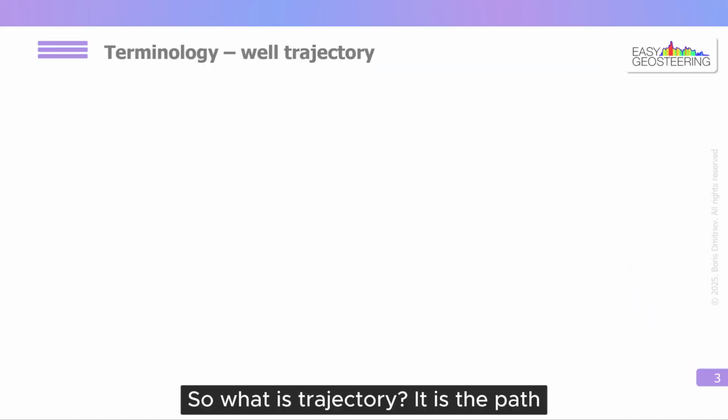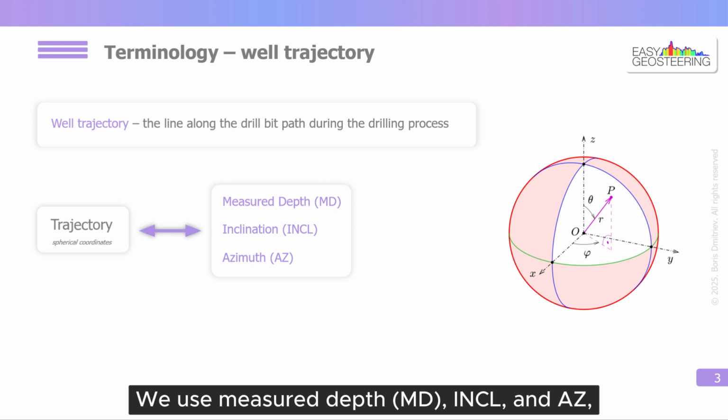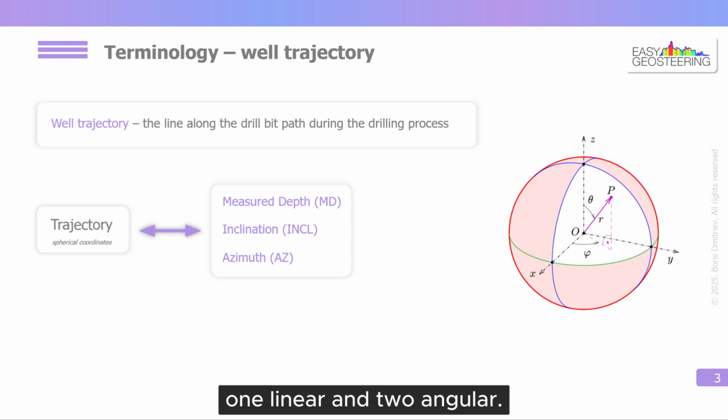So, what is trajectory? It is the path along which the drill bit moves while drilling, a three-dimensional line in space. To describe this line, we need 3 coordinates. We use measured depth, inclination, and azimuth, which are analogous to spherical coordinates, 1 linear and 2 angular.